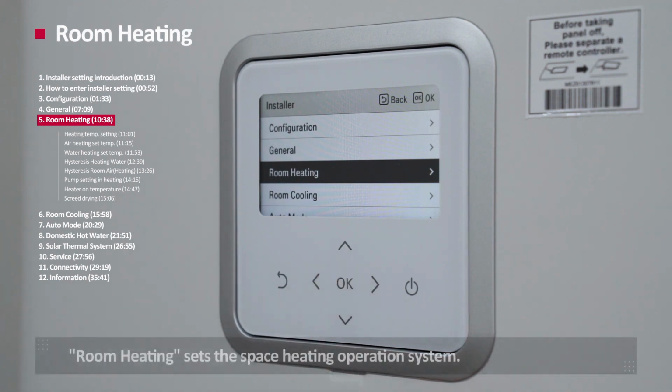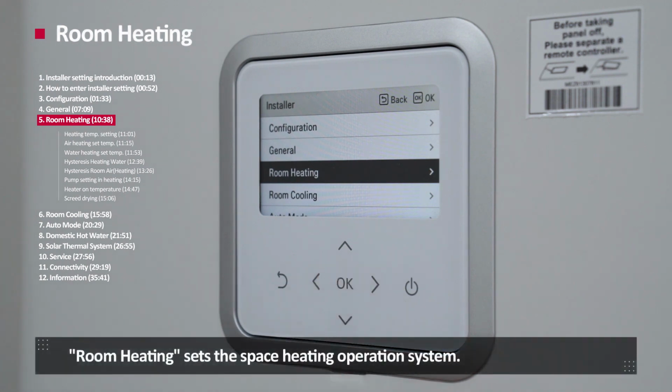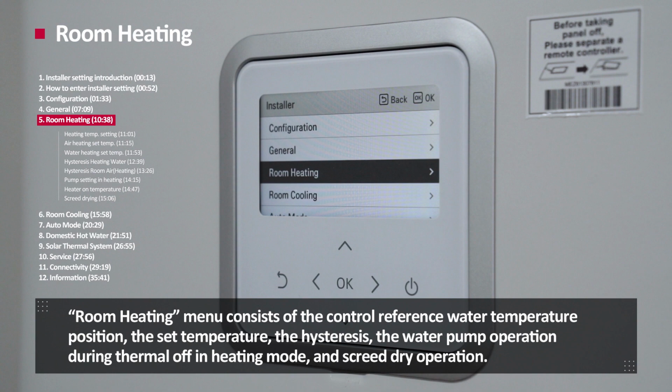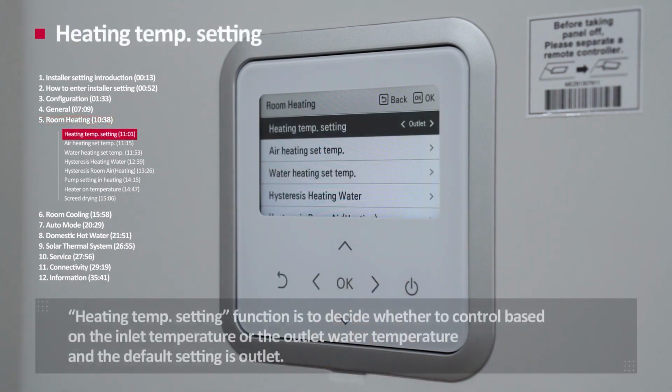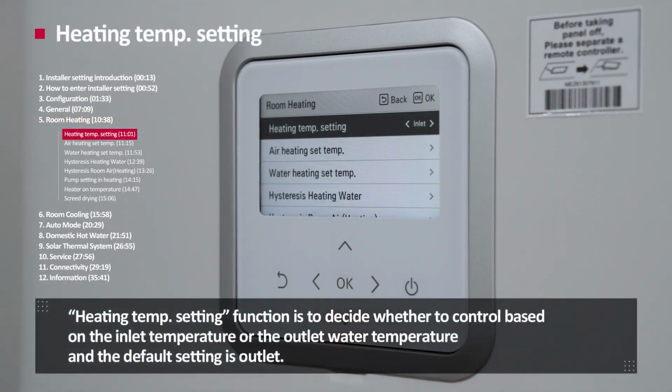Room heating. Room heating sets the space heating operation system. Room heating menu consists of the control reference water temperature position, the set temperature, the heat statuses, the water pump operation during thermal off in heating mode, the screed dry operation. Heating temperature setting. Heating temperature setting function is to decide whether to control based on the inlet temperature or the outlet temperature, and the default setting is outlet.